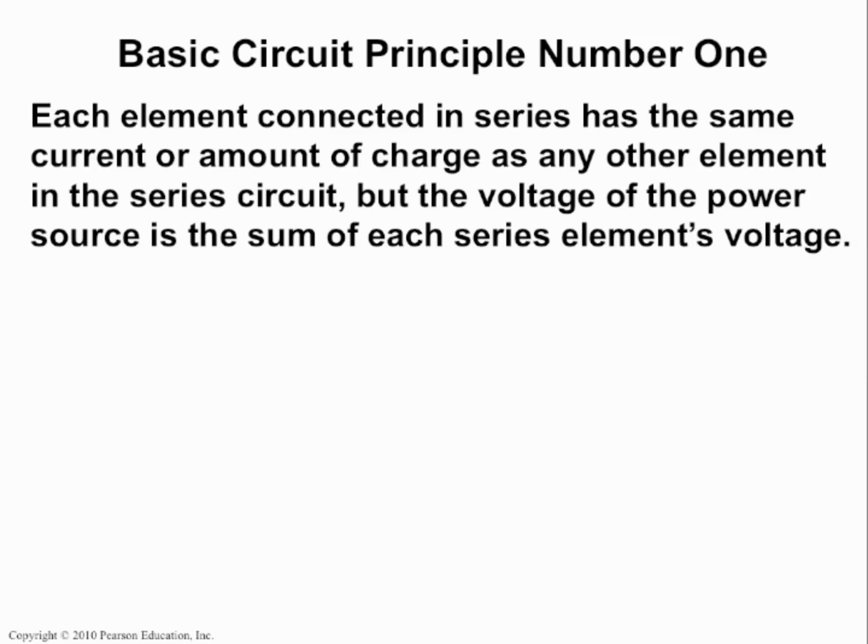And that brings us to basic circuit principle number 1. Each element connected in series has the same current, or amount of charge, as any other element in the series circuit. But the voltage of the power source is the sum of each series element's voltage.